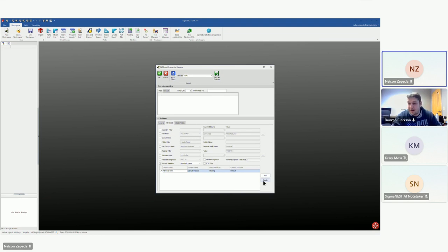Like a layer in SolidWorks you're talking about? Yeah, the sketch layer, yeah. Okay, I'm following. So then you can do it this way to bring those in for automatically assigning it to be etched or marked at the machine and not having to do that setup after you get the part imported. Very good.